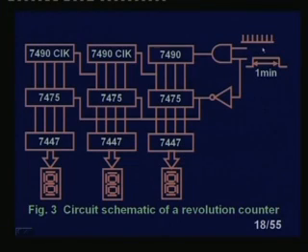So what we are doing here: in one input of the AND gates, I am giving this clock pulse, and in the other input I am giving a pulse whose mark is 1 minute. Then it will have a gap, then again it will come. It is only 1 minute wide, a repetitive pulse obviously. Whenever this is high, it will activate the counter, and the counter will start to count from 0.